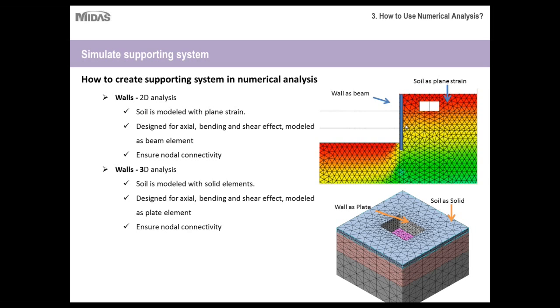And since the wall is connected with the soil strata continuously, make sure the nodal connectivity is maintained. Your beam member should be divided all along the length and connected to the soil strata.